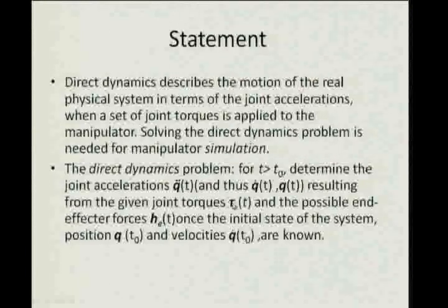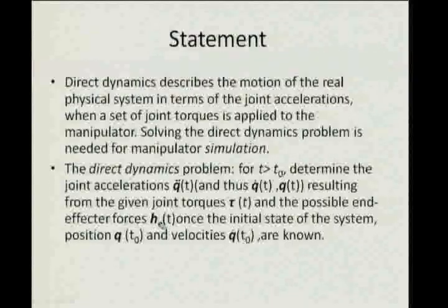right. Now, I am also given the torque which is being applied as a function of time at the various joints and the possible end effector forces HET. Now, how will you know the end effector forces? If you are holding a mass in the end and you are moving it over a specified trajectory, you can simply write mass times acceleration, and then you can add the g gravity component on the mass, and then you will know the end effector forces.